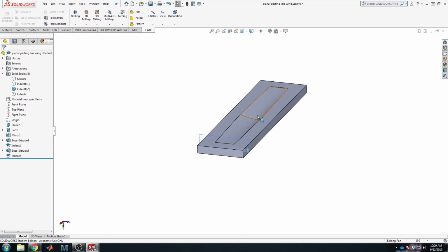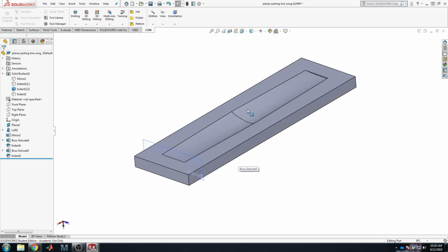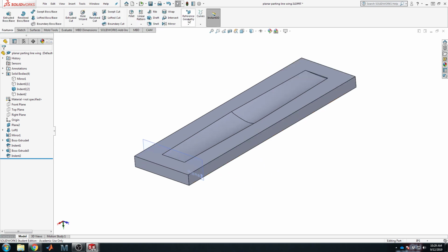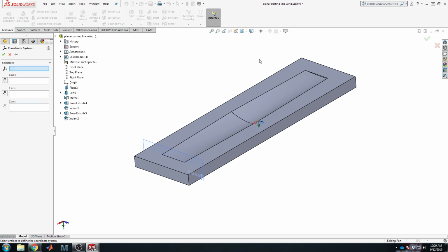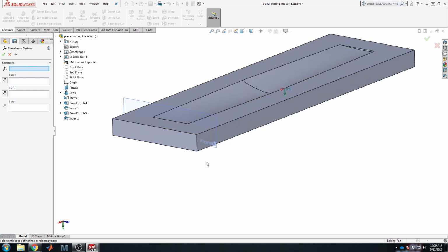But starting simple, if you had this large wing mold and you wanted to cut it, the first thing to do is establish a coordinate system for the cut. And this coordinate system should match the CNC machine you're going to use. There are 4 things you have to define. Really, it kind of comes down to 3 because one of them's implied by the others.